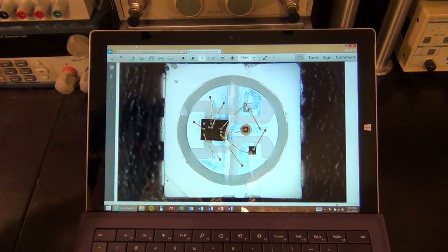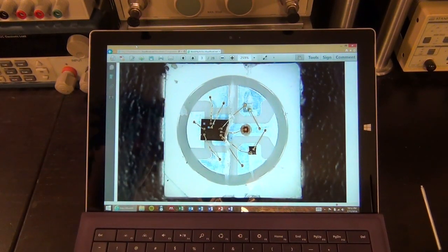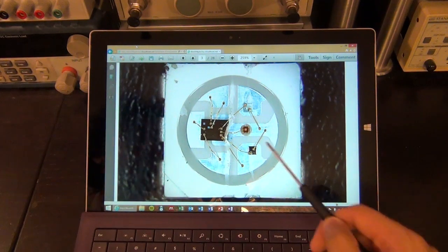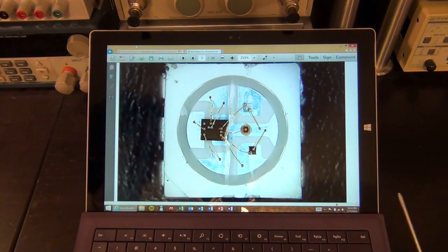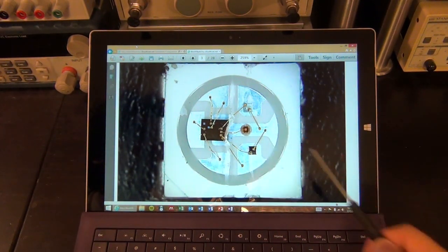And then you can imagine this being extended to many, many more LEDs. It doesn't have to be 2, it could be 128 of them. So you have to keep pushing data in there, and once you've pushed enough data, then you hold the data line low, and then all of them will light up. So this IC will take care of all the PWM and all the other details. But it's interesting to take a close look inside it.